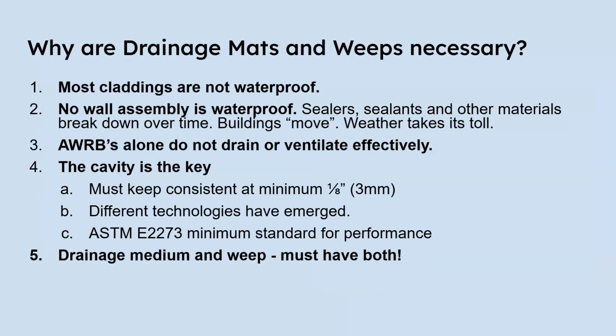Ideally, drainage mats and weeps would not be necessary because all systems would be face sealed and never suffer any kind of degradation caused by building movement or thermal inefficiency or cracks or sealant that wears out or any of the other million reasons why water can ultimately go around a waterproof cladding and get into a wall. So they're simply necessary because of the way buildings are designed and need to be maintained and the practical inefficiencies of some of the products involved.